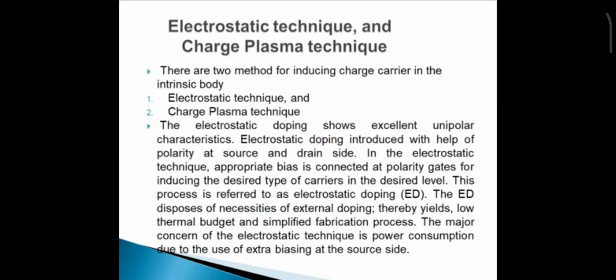Electrostatic doping does away with the necessity of external doping. Thereby, it yields a low thermal budget and it also simplifies the fabrication process. The major concern of the electrostatic technique is power consumption. The power consumption of the device is high due to the use of extra biasing at the source drain side.